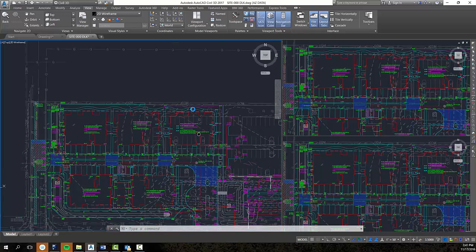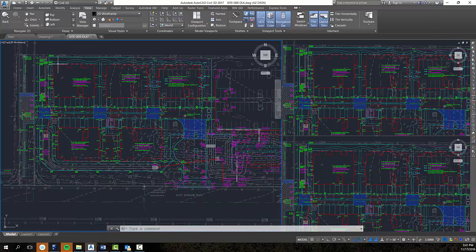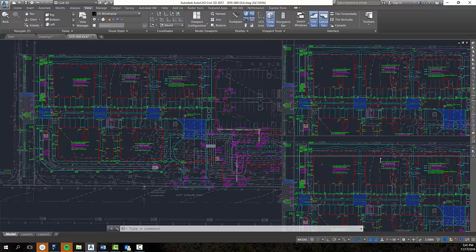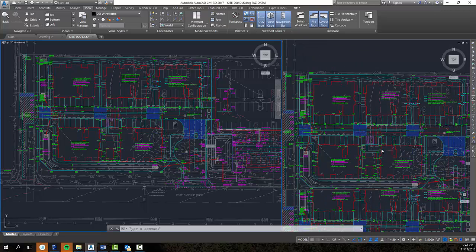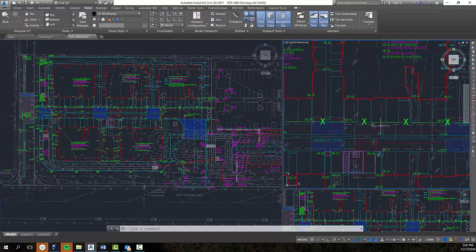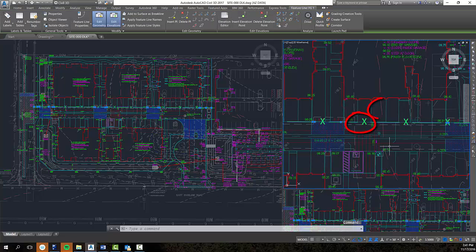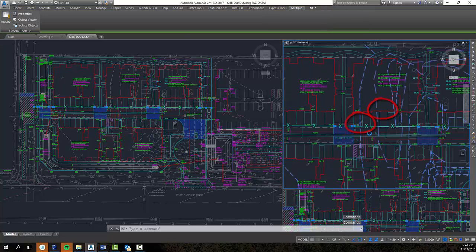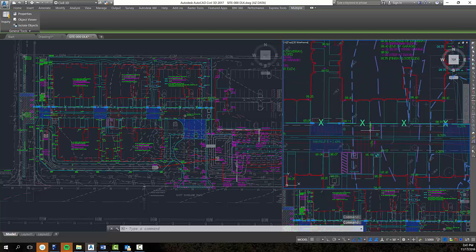If you've got dual monitors, it's kind of nice to expand this whole session over your dual monitors and put this viewport split right down the 2 monitors, and then you've got 2 big work areas. The reason for this is that it works well when you're working in 3 dimensions here. So what I'm going to do is grab that feature line, maybe the existing base map, just so we have something to base our rotation on.